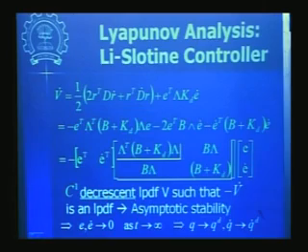If you implement this, you will see very clearly that if you set the gains appropriately, then immediately your actual trajectories will converge to the desired trajectories with this tracking controller. So if you compare the results of this simulation with your corresponding computed torque control strategy, you will find significant improvement for this controller. So it is a very high performance kind of tracking controller that we have.